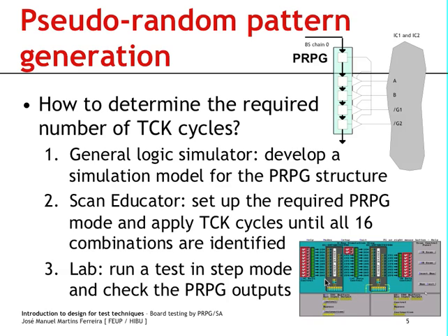But once you have it up and running, then it will be very practical, because you can just load the initial seed value, and by ticking the TCK pin you will be able to check the sequence of logic combinations generated at the 4 pins driving the cluster inputs, and then you just have to cross each combination as it is generated until you have generated all 16 possible patterns.